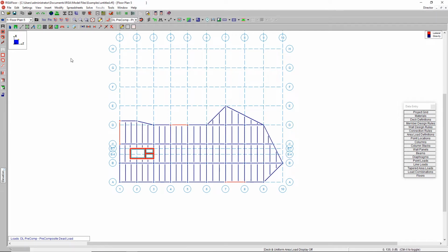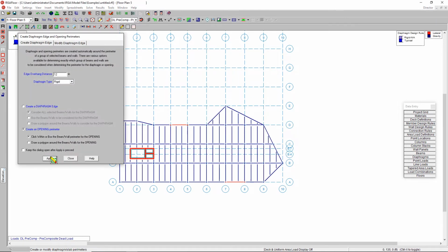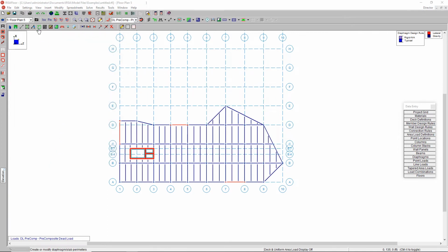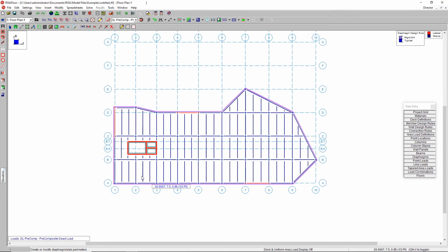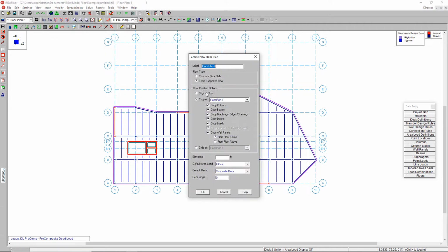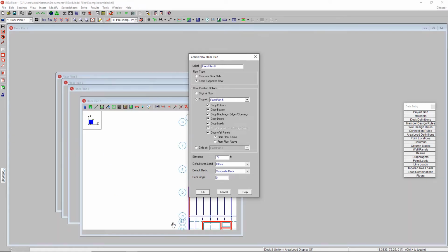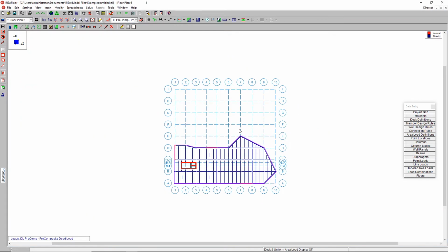We can put on the diaphragm one more time back onto the structure. I'm going to go ahead and put that diaphragm right back on. Oops, I think I'm in there we go. Diaphragm edge, there we go. And we can start to build the next floor level. So we can go ahead and say, let's insert floor, and we'll be copying floor plan 5. We're going to copy that at 72 feet. And everything else is remembered. I can just say apply, and I go from here.